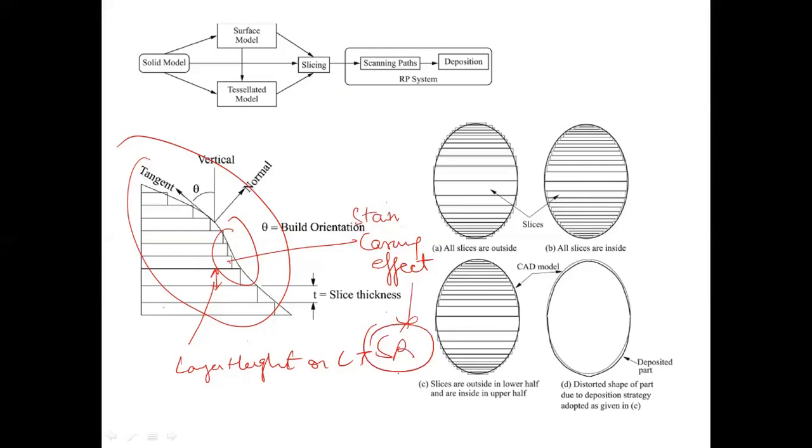If you move your probe across this profile, there are peaks and valleys. This is a peak and this is a valley. Every time there is a peak and valley, when you move your surface roughness probe across this line, you would observe surface roughness data being generated.